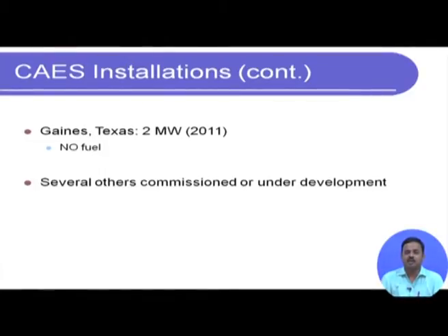All right. So, in this class we wrapped up our discussion on compressed air energy storage. We looked at the two different types, diabatic and adiabatic plants. In adiabatic plants there is no heat loss, but this is not very practical. In diabatic plants there is heat loss, so you need additional energy to heat up the compressed air before it enters the turbine. Then we saw a couple of installations, the two most famous ones, Huntorf and McIntosh, and we looked at how they work, some of their numbers, their efficiency numbers and so on.